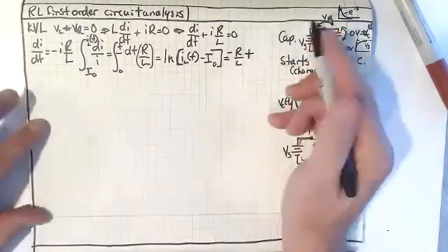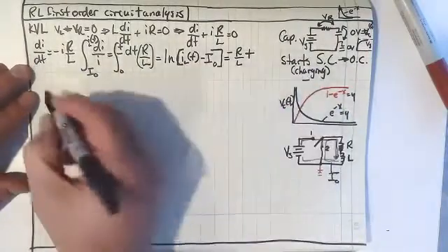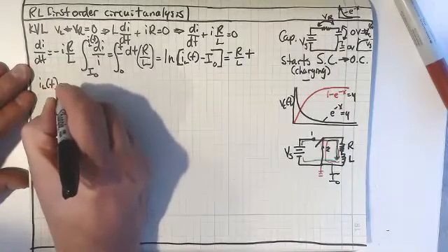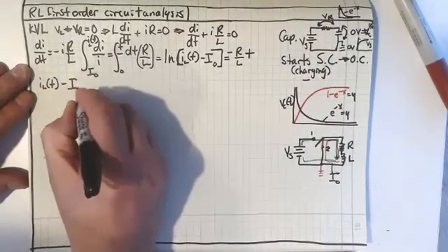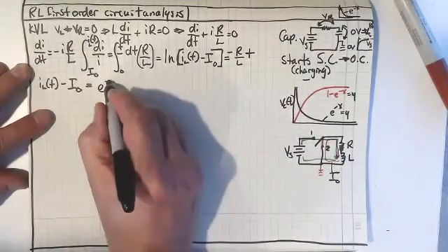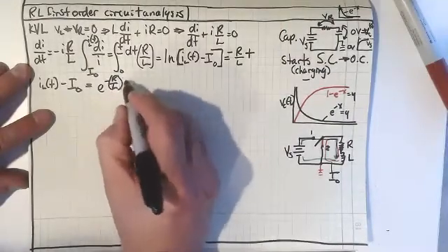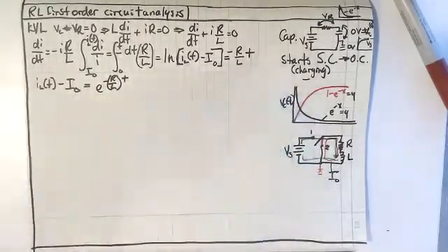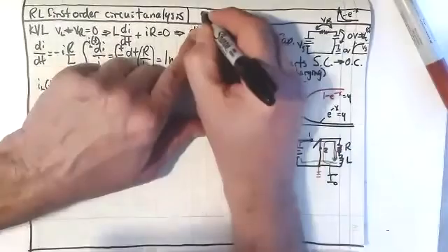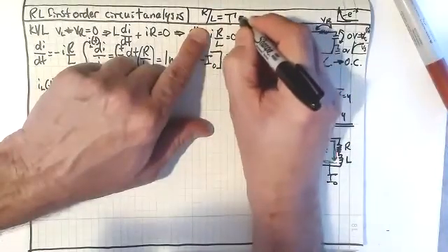All right. Now let's take the exponential of both of those two sides, and so what I would get is I sub L of t over I sub 0 is going to equal e to the minus R over L, and I'm going to keep that separate, times t. Because what is R over L, right? R over L equals our time constant.